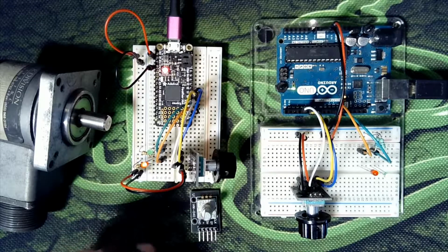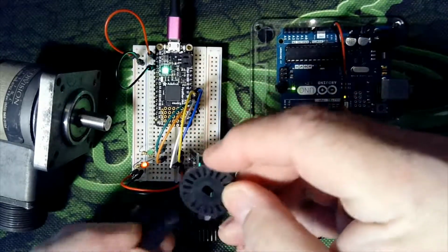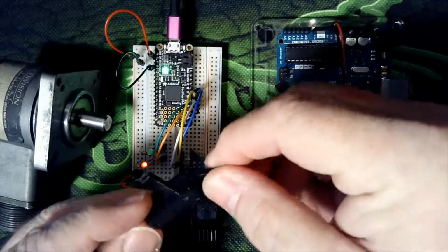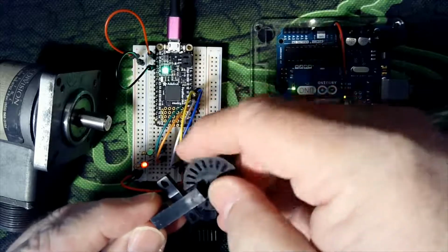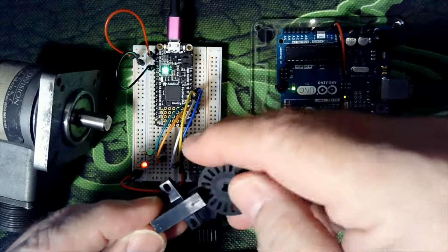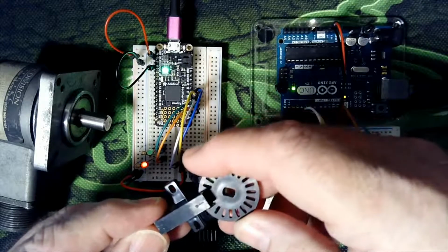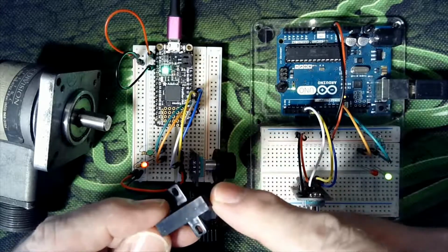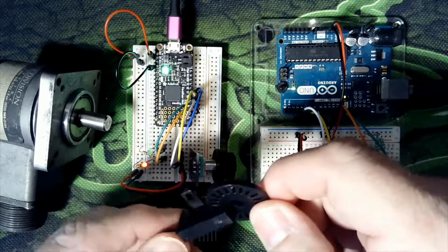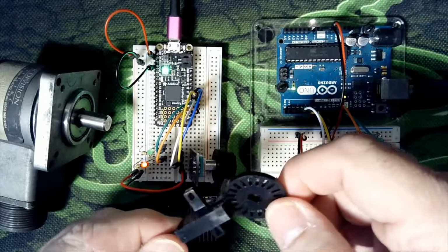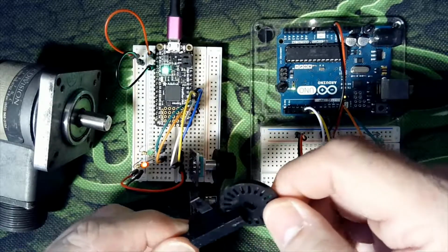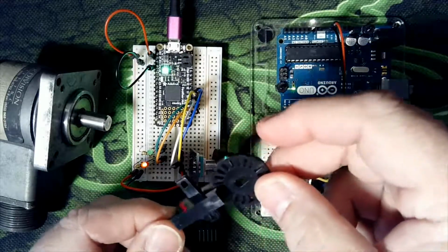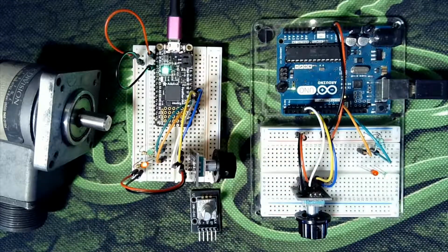Basically what happens here is this disc is mounted on a shaft, and it is put in between this, and then as it turns, hard to see the light there, the little beam of light goes from the emitter to the detector. So as it turns, the light gets seen and blocked, seen and blocked. So this is a single channel encoder. It only has one output pin, or input pin into our PLC or into our microcontroller, but we could use it for counting things very quickly. We could use it for RPM calculations and things like that. So that's something that can be used.